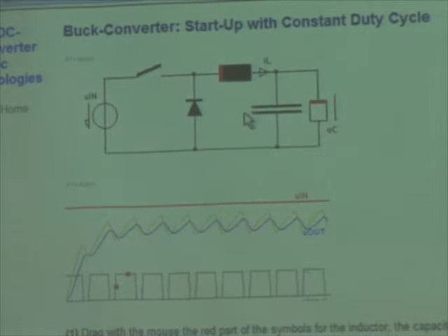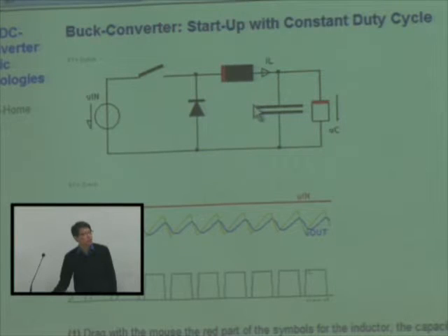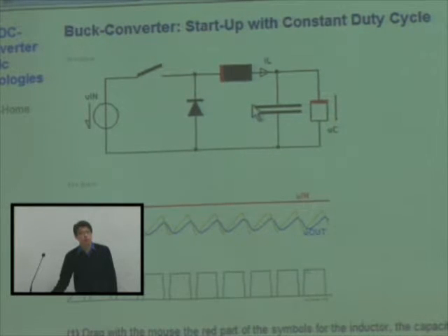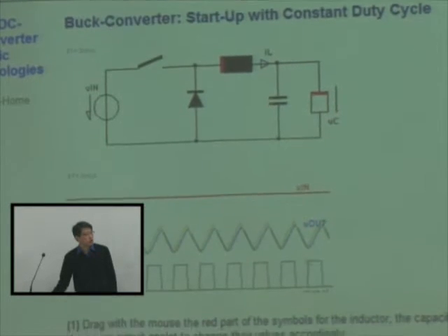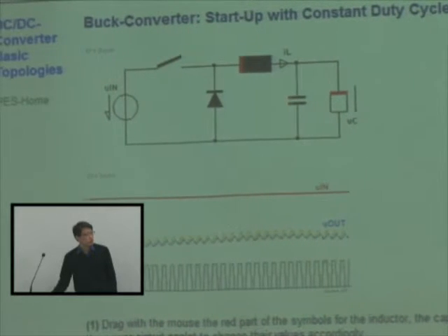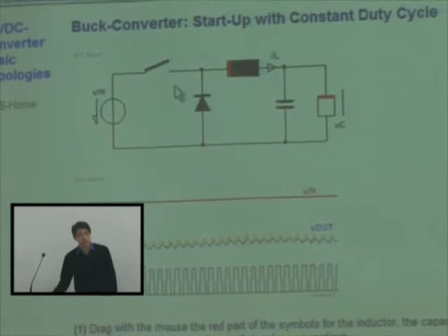So is it good or bad to have large capacitance? Good, right? But the large capacitance, as you can see in this graph, takes more volume and weight and is more expensive. So large capacitance is costly for designing the converter. So it's good that we obtain small capacitance and then increase the switching frequency. And what limits the switching frequency? The switching loss.